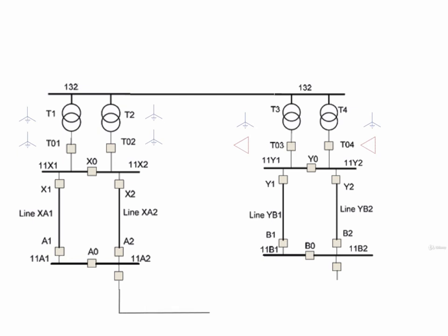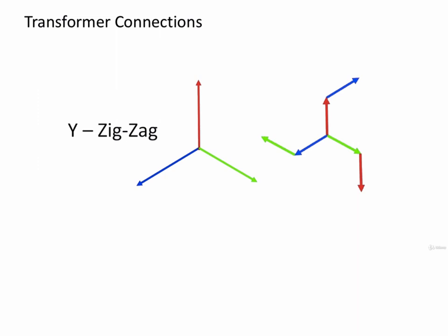As the system grows, at some point it would meet on the low voltage feeds, and for logistical reasons it might seem practical to parallel the systems. Of course, the problem here is the 30-degree phase shift difference on the secondaries of the transformers and their connecting feeds. There is a solution to this, and it is accomplished with the aid of the star zigzag, or another name for it is the interconnected star transformer,